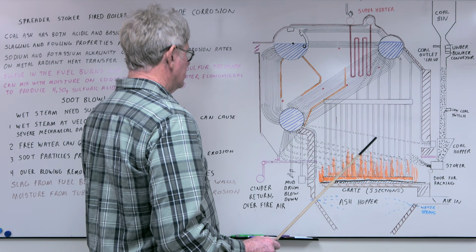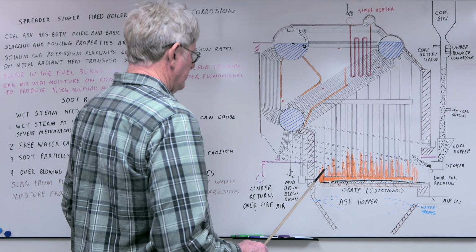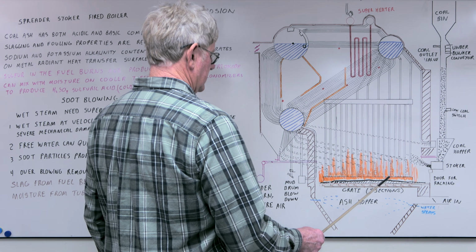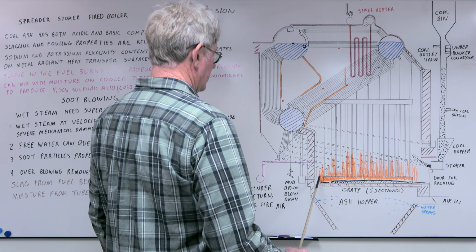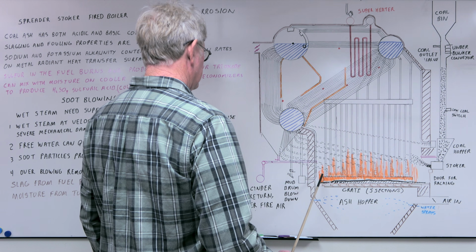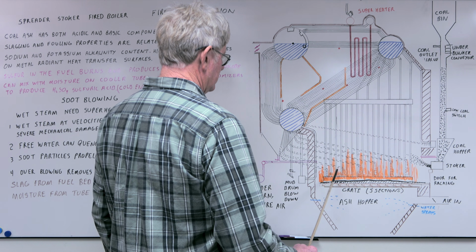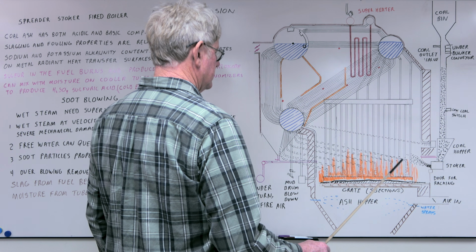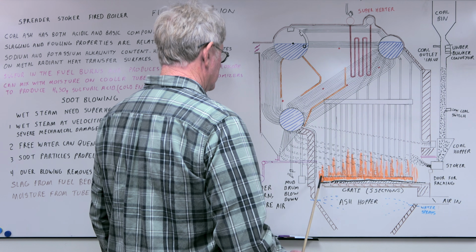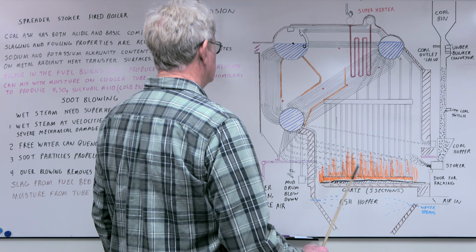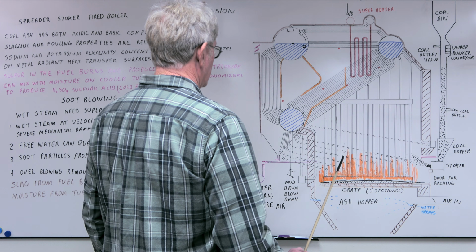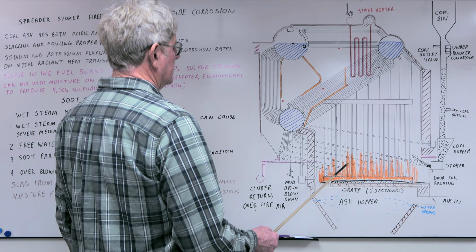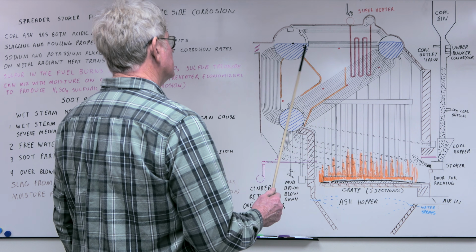Basically, with this boiler, it's fairly simple. You just had to watch. If you knew what was in your coal ash, you can figure out how high you can run the bed without melting it. Say you get more potassium and sodium, the lower the melting temperature, the more likely you are to have clinkers form, melting the whole bed in one solid mass. Like say iron, there's a bunch of different compounds that'll play into your ash temperature. But the sodium and potassium, that's really big on pulverized coal units. For the precipitator to work, you had to have the resistance of the ash right so it precipitates out.